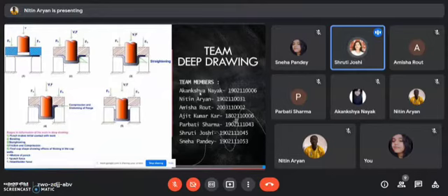Last, tension. With further increase in the applied load, almost all the metal blank sinks into the die cavity, thus forming a long vertical wall. The remaining blank part takes the form of a small annular flange. The vertical wall is subjected to uniaxial tension.